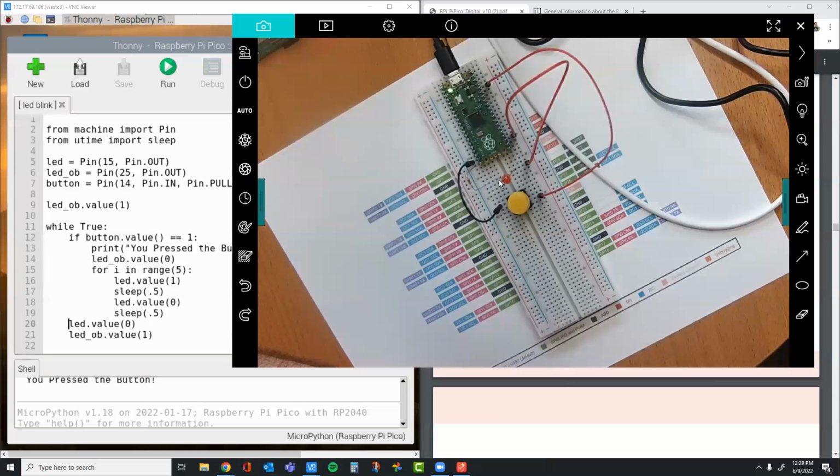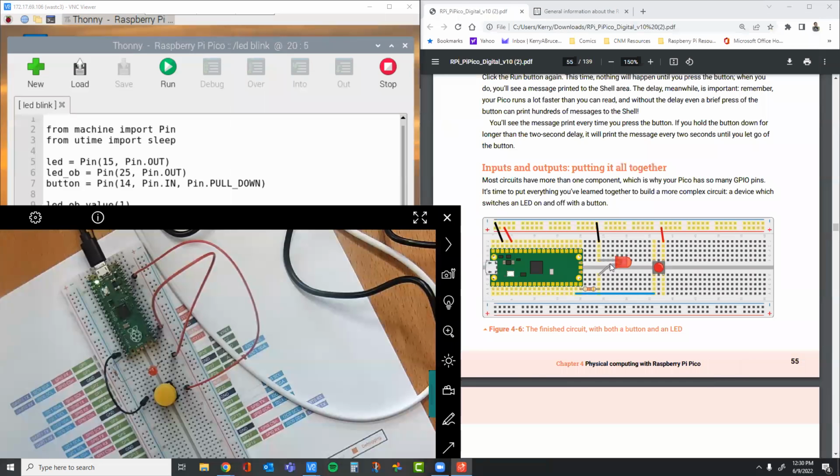In the material, in the book, it talks about LEDs, and LEDs are polarized, right? There's a plus and a minus side. So the electricity needs to flow a certain way for it to work. Which is why in the diagram, there's a bent leg here. That's always going to be the long leg, and then the short leg will be the one that's not bent.